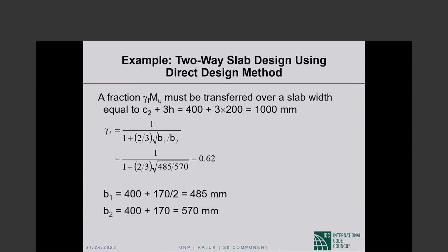So this is an exterior support section. This critical section for shear is something that has not been discussed yet. It is tomorrow's topic. But anyway, this is an exterior column. So one dimension is the column dimension plus 1/2 of d, the effective depth of the slab.